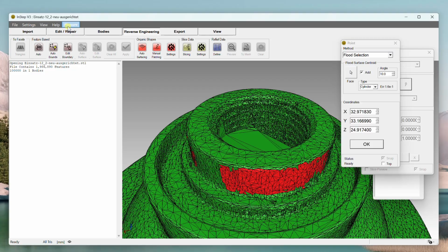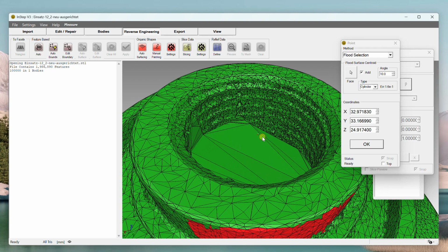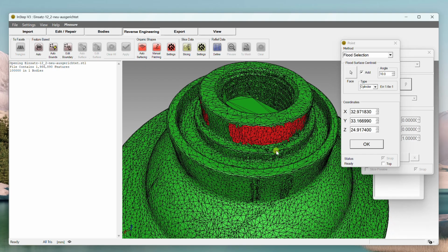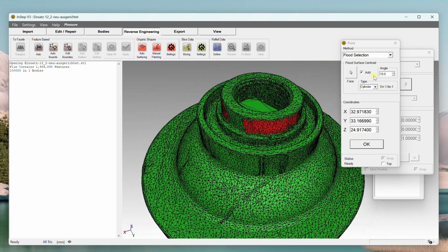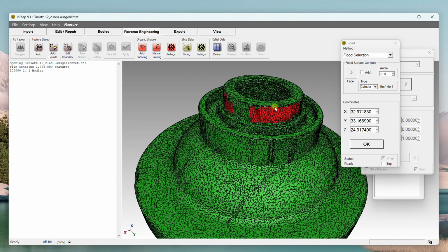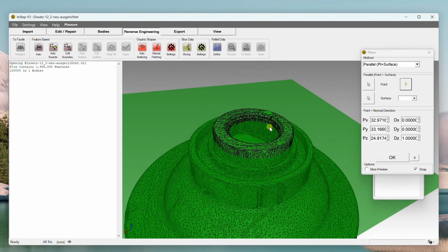The other option we have is to use the measure tool that we've seen in previous videos and get a number of data point samples, then use that as a way to get an idea of where that point should be, and then we could just type it in. But for this case, this is probably the option to use, and we can apply it to the other surfaces as well. We can uncheck this and start selecting down here or on the side to get a different center point. Then we can compare those numbers. But for this case, I'm just going to go ahead and say OK. That's the point we want to use.